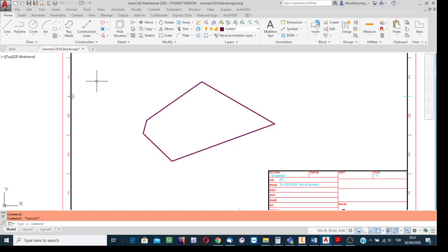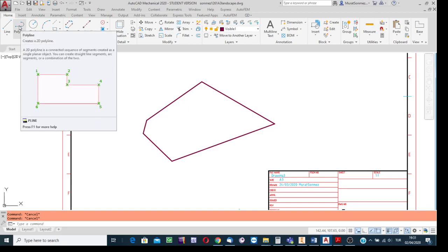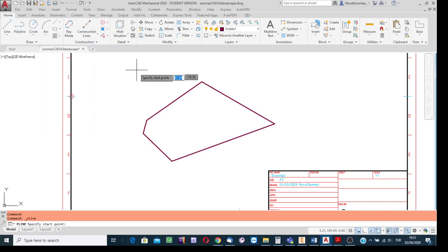This is the indication that the lines are connected to each other in sequence. Instead of wasting time clicking on this title, selecting the region option and windowing method and pressing enter, it is recommended, if you're going to use the lines for having a region in the end, and thereafter apply an extrusion, revolve or sweep process, in general a solid model creation process, to select the polyline tool and create the lines using that facility. After starting the process, the things are the same to deal with.